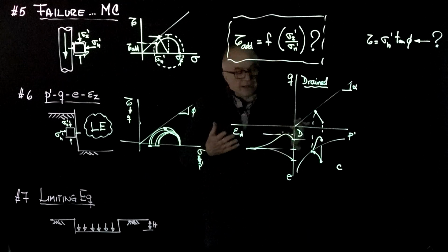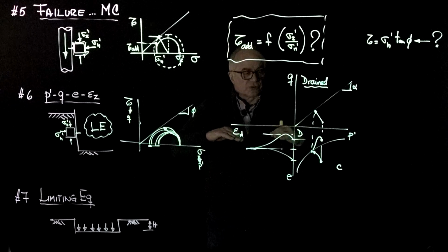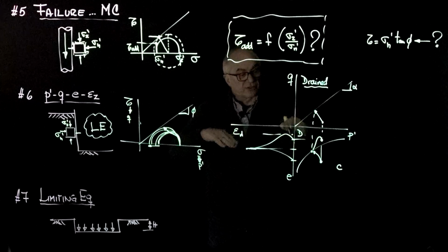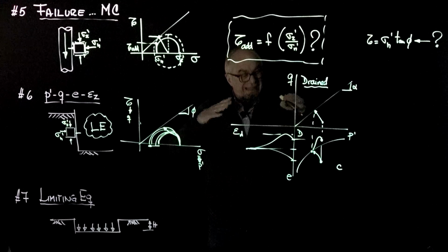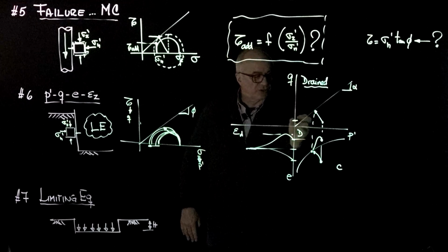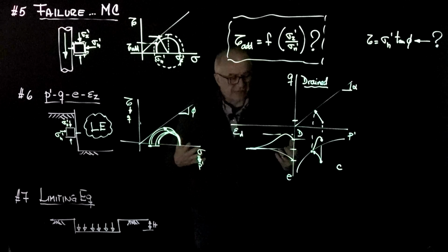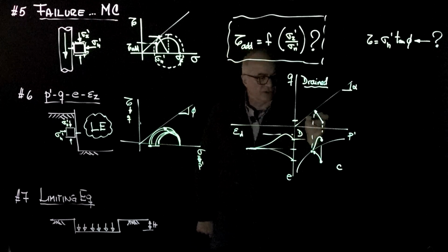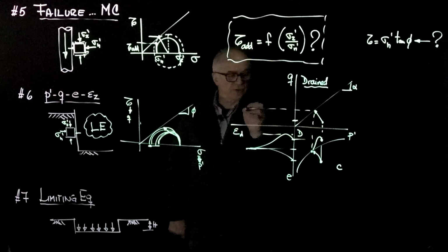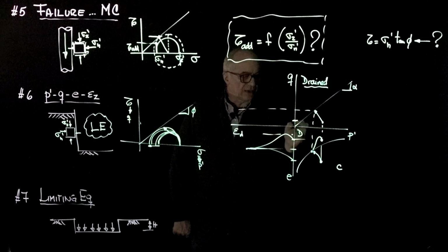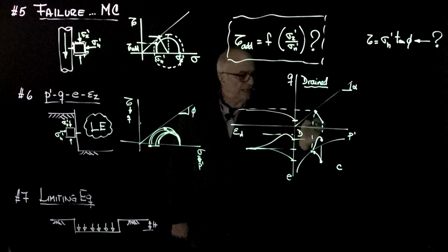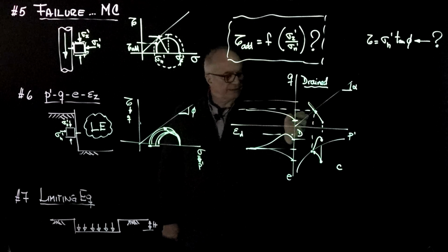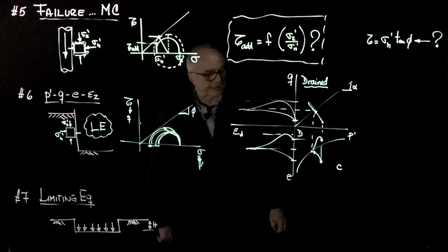In the upper part, notice that I'm actually going to shift the q. Deviatoric is really being the additional one starting from this point, not from 0. We already had some amount of deviatoric stress because of the K0 condition. The points are going to end up here, and the contractive one will evolve in this direction. The dilative one may actually overshoot and come back, and it will look like that.